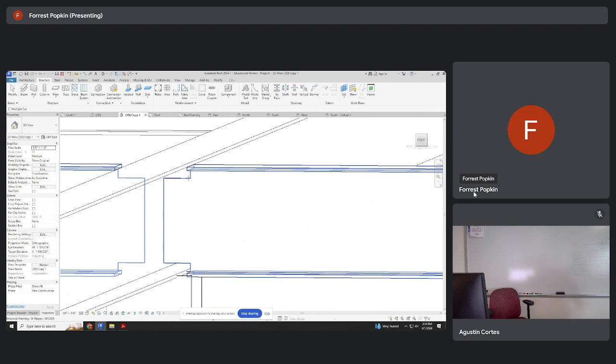But then the problem is, as I just got done talking about, how do I attach it? So in this particular instance, it's kind of not showing it accurately because my girder and my beam are the same depth. So it's kind of unrealistic that you would have your I-beam look like this, and then you're just going to notch out the entire thing for your other beam. What's probably going to end up happening is something more like this. Your beam is a little less deep, so that part doesn't get cut.